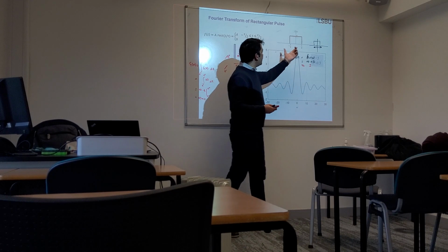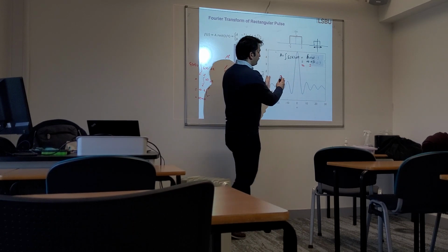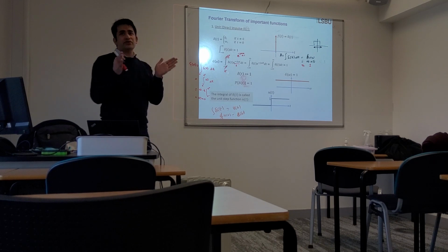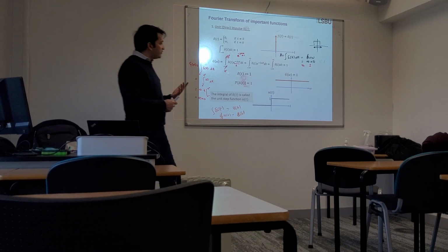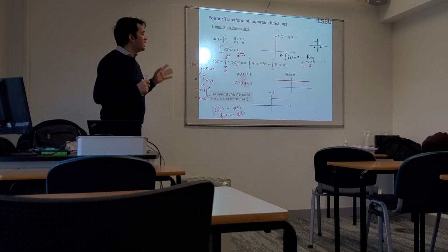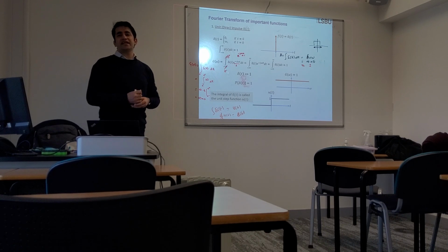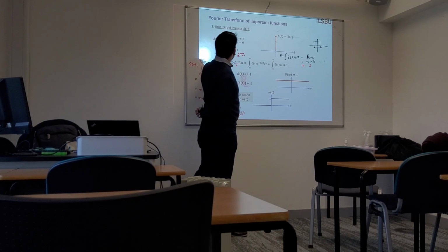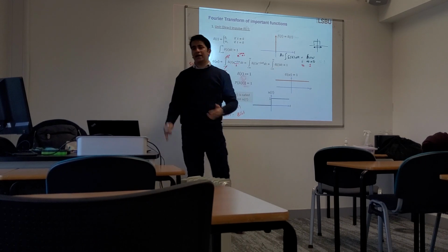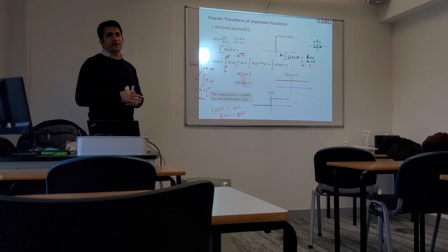However, on the other hand, if you squeeze this width, you will see that this triangular wave will keep on expanding. So from here, we came to know that if we keep on reducing the width almost to 0, the Fourier transform would indirectly be a straight line. So if you want to find the Fourier transform for the Dirac delta function, we will say that it is equal to 1. So that's why we say that the Fourier transform g of w for the Dirac delta function is equal to 1. And this we somehow obtained from making an analogy with a sinc function.